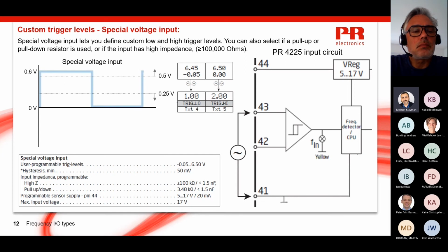The on voltage of 600 millivolts is lower than the high trigger levels established for PNP or TTL inputs, so selecting those input types will not work. The signal simply doesn't reach the trigger level for these input types, so the frequency would not be measured. Also, the off voltage does not go negative, so selecting a tacho input won't work.